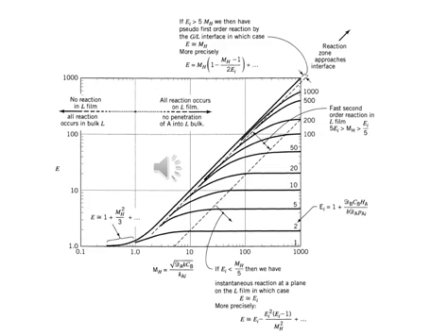Then we have other cases. Looking at the bottom, we have a case where EI, the enhancement factor for an infinitely fast reaction, is less than the Hatta number divided by 5. In this case, this is how we calculate E. So E becomes equal to EI.